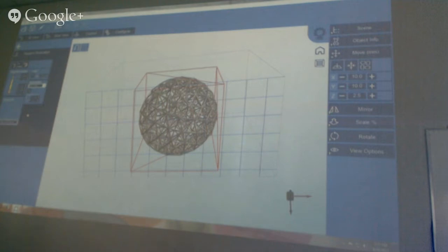But then other things, depending on features, a 45-degree overhang might be a challenge if I need good part shape. I want to make sure that a particular 45-degree angle is perfectly straight. That might need support structurally to keep it straight.